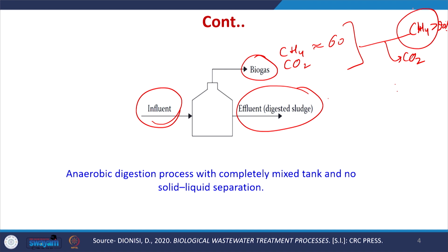So, for this technology of anaerobic digestion, there is a lot of demand for treatment of wastewater which contains a large concentration of organic loading. It is also being used for treatment of municipal solid waste, in particular if the solid waste is already separated and we have the biodegradable fraction which is used.